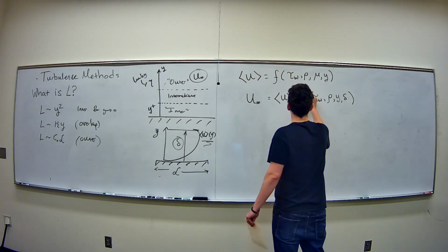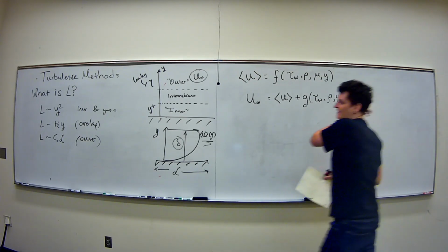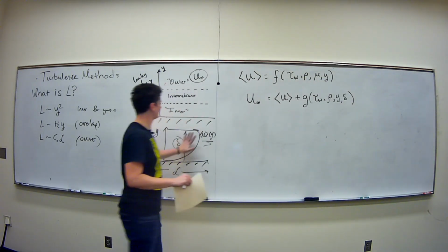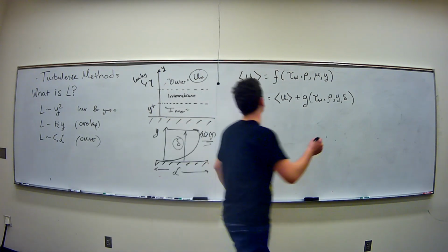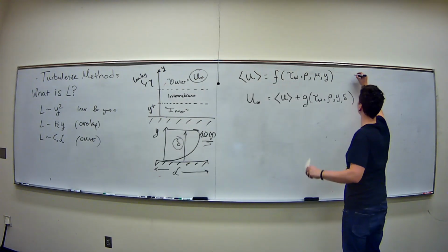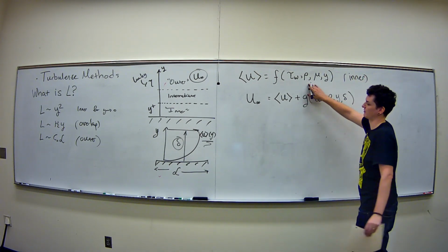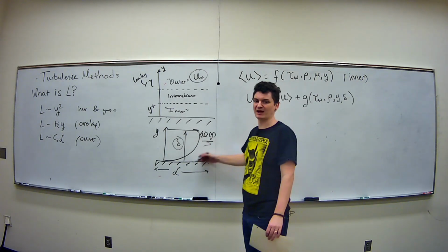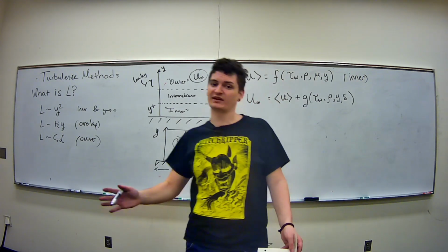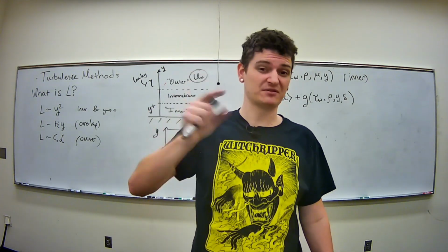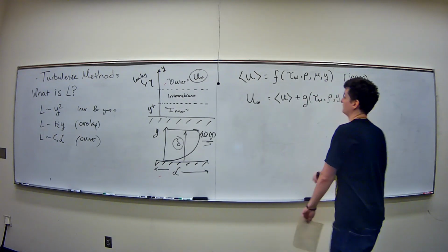So another function g. These functions make sense because you're saying that the mean flow occurring in here, if I'm in the inner region, the inner is my assumption on this functional form. The inner region will be dominated by viscous forces because I'm close to the wall. That still holds in turbulent flows. Don't forget it. And what also still holds is no slip still holds. Very forgotten about a lot.